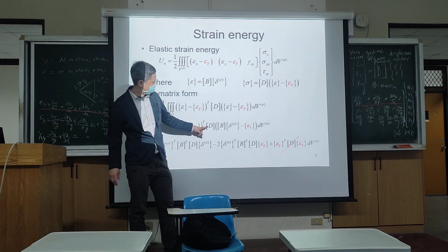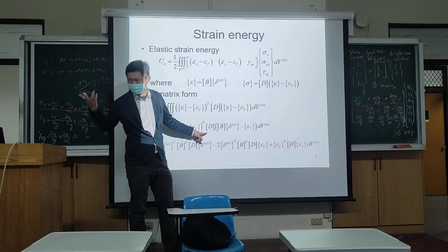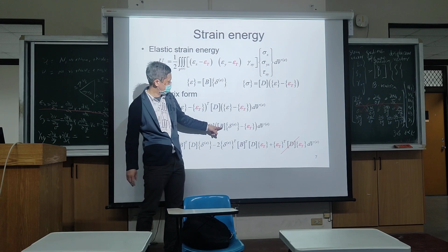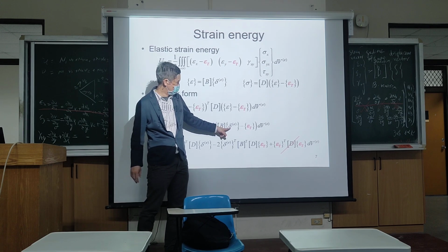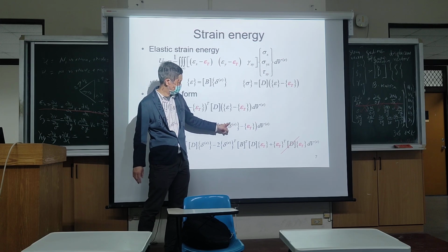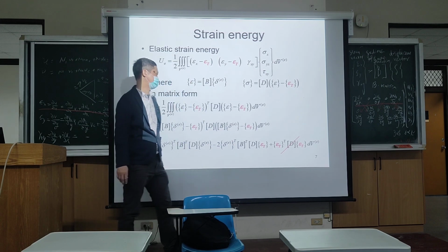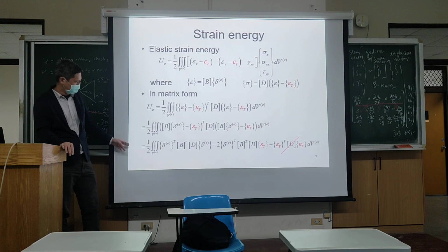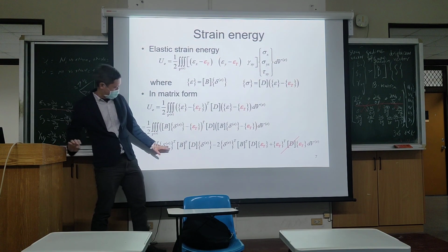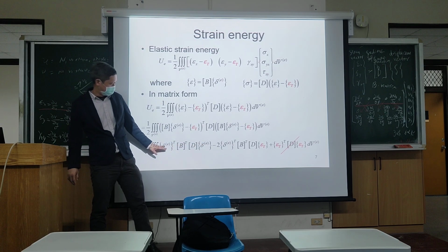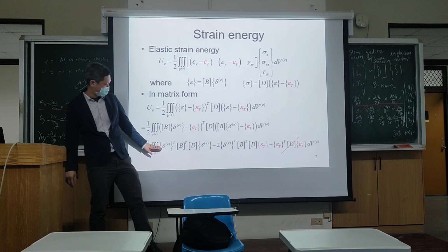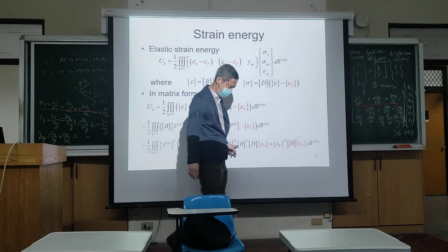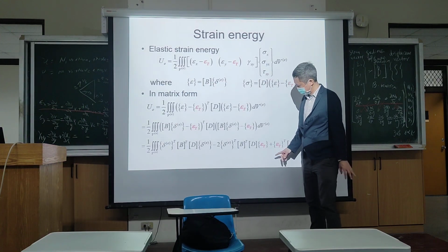Mechanical stress is the D matrix, equivalent to your Young's modulus, times the B matrix times the displacement minus the thermal strain. If you now do the expansions, then you see the part associated with the displacement vector remains the same, but now you have one additional term.